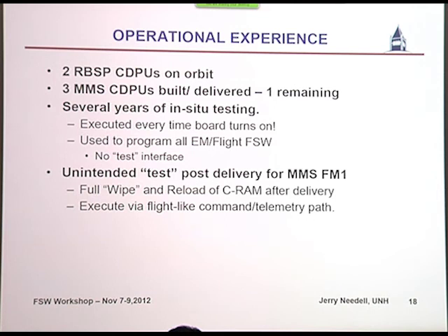You said commands come in through a non-maskable interrupt. That means the hardware already does the decoding? Yes, the FPGA brings in the command string, a CCSDS packet in most of these cases, and parses it into a FIFO. If there are less than 2 words with the command, it'll put them in direct registers. If there's more than that, it puts them into a FIFO and then sends an interrupt to the processor.